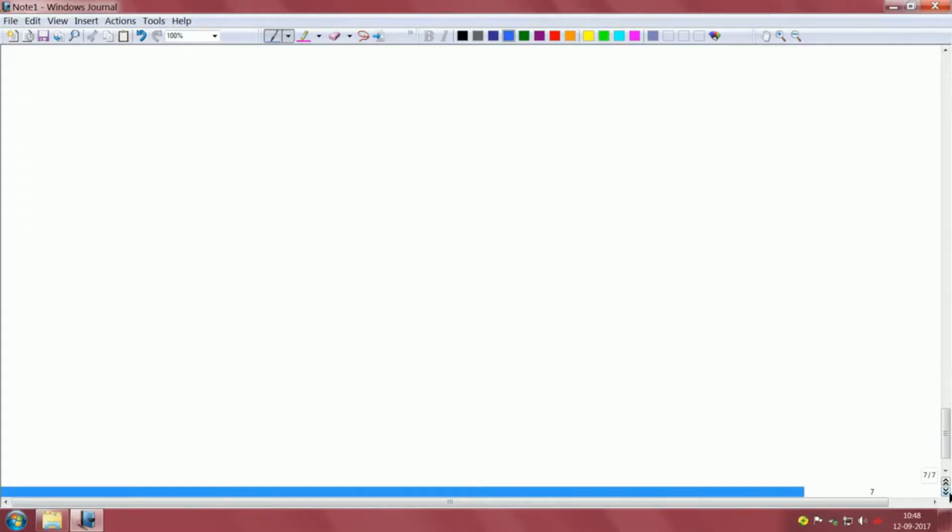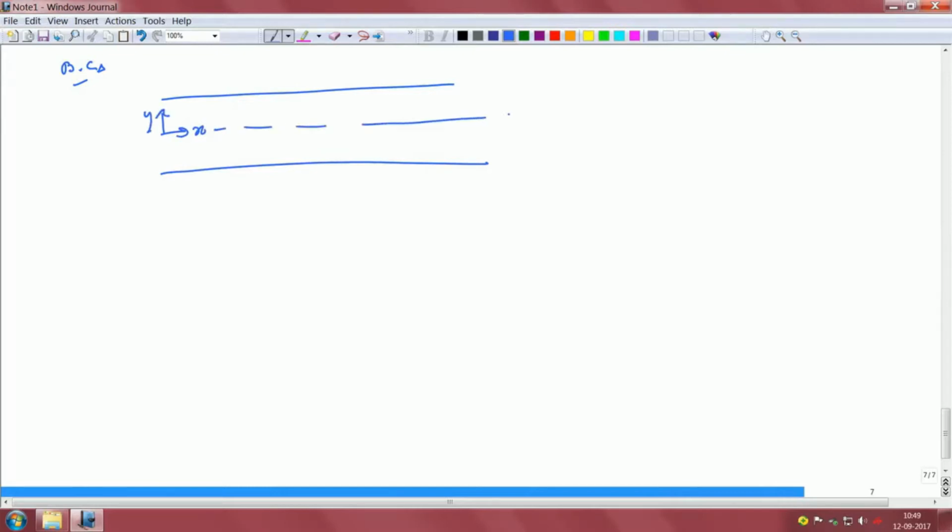Now that we have this particular equation, we don't need boundary layers anymore. I mean, we don't need scaling arguments anymore. We can simply solve the equation from first principles, right? So we can write the boundary conditions first. As we write the boundary conditions, let's take this as x, this as y, this being the axis, right? You can have it in any other way that you want, doesn't matter, right? So u is equal to 0 at y equal to plus minus d by 2. The simple reason is that these are walls, so the no slip condition applies.